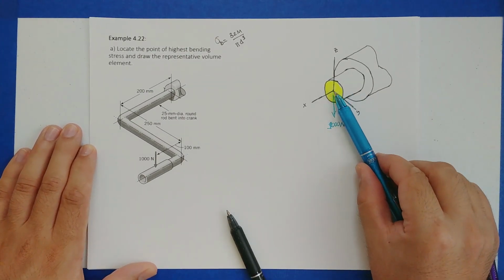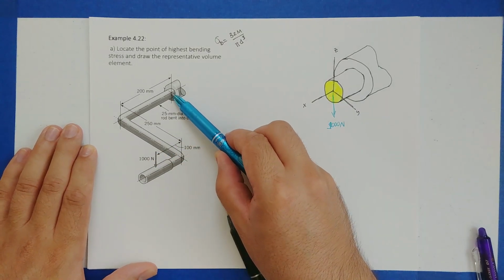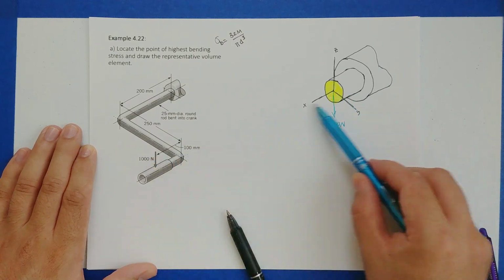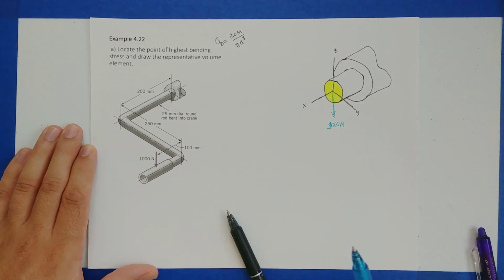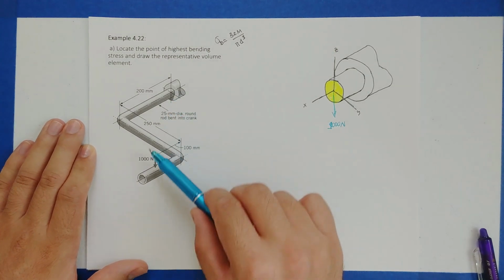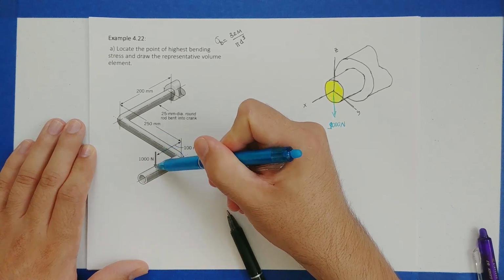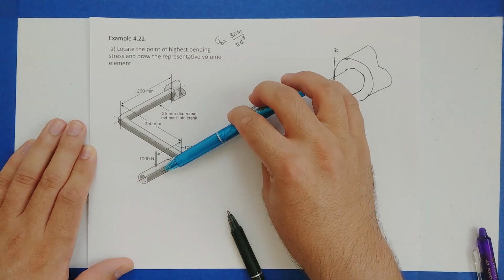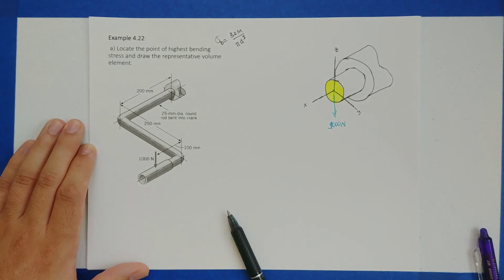Now, another way to say this is I'm trying to figure out what is the resultant of this force at this point over here. Well, we know that the resultant force is going to be a force of the same magnitude and direction, but also that this force can generate some moments, right? So how do we know that? Well, whenever we move a force anywhere that is not in its line of action. So in this case, if I slide this force up and down in this free body diagram, I don't have to worry about moments. But because I slid it over here, I went maybe this way and then that way, I need to figure out what those moments are.